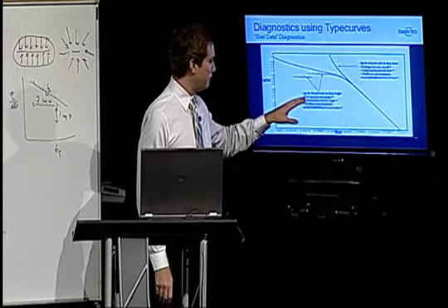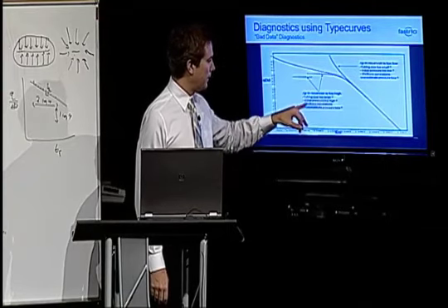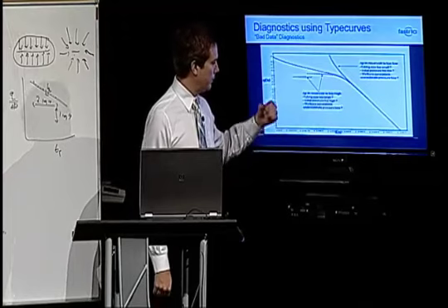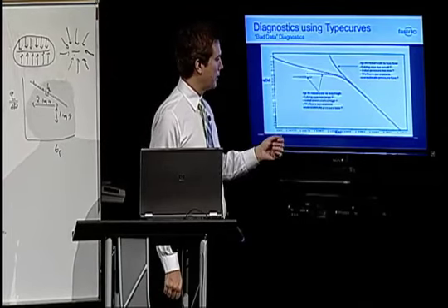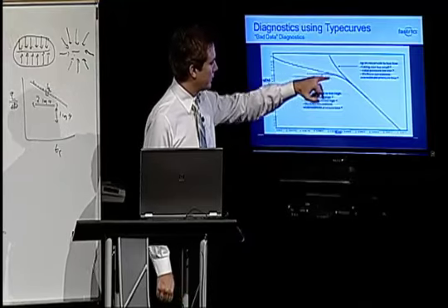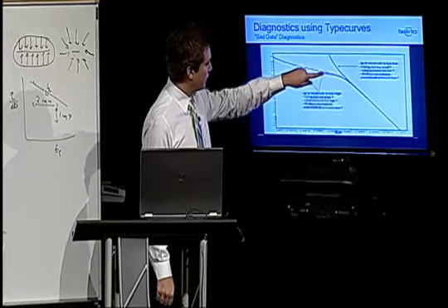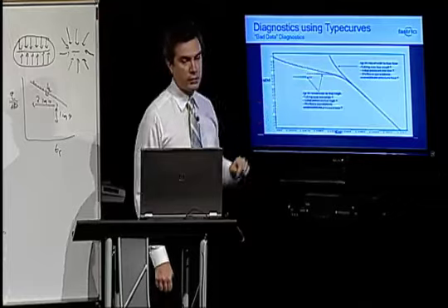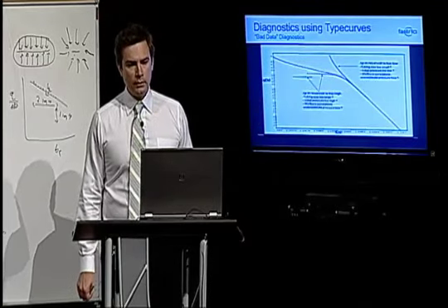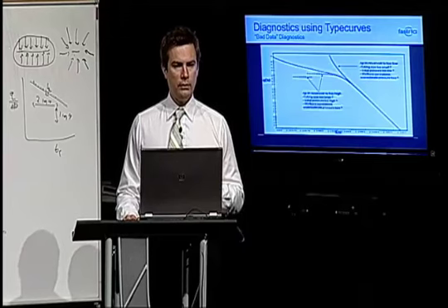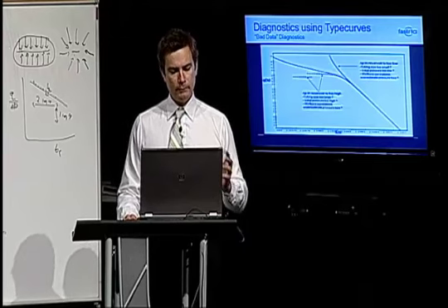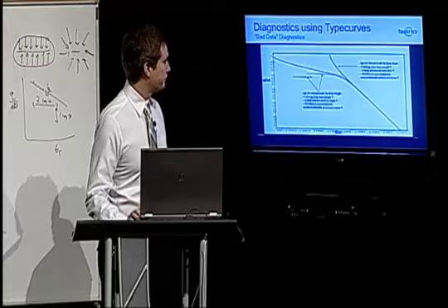If, when we do that, we made a mistake, any one of these mistakes, tubing size too large, initial pressure too high, wellbore correlations underestimate the pressure loss, we may end up getting a diagnostic that looks like this, and the data was supposed to be on that curve, but it didn't match there, so we're going to get the wrong answer. So just be aware of those sorts of things when we're doing the calculations of pressure, there could be some problems introduced there.